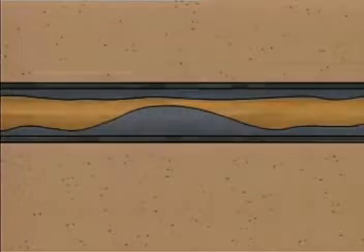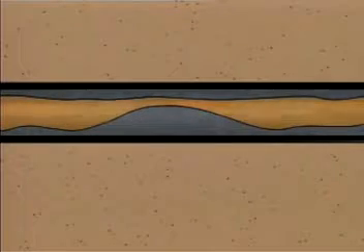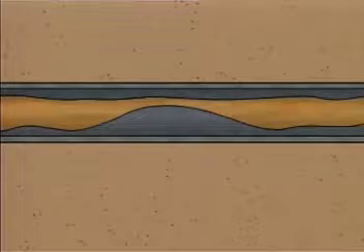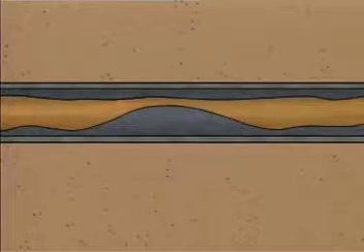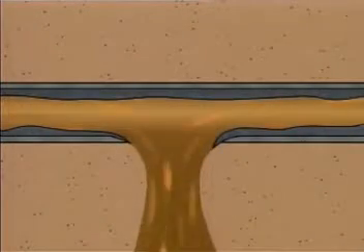Carbon deposits insulate tube walls, which reduces the amount of heat that is carried away from the tube by the process fluid. If this situation is not corrected, the tube could overheat, weaken, and eventually rupture.